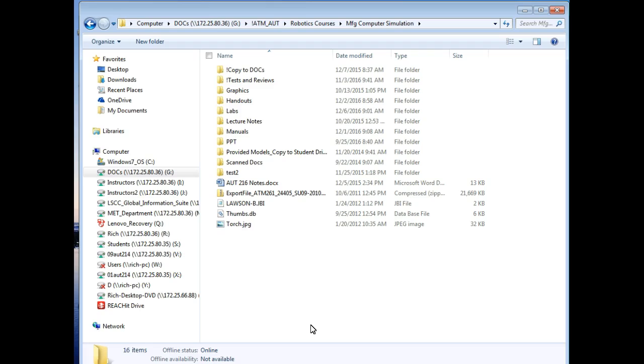Locate it, save it to the flash drive. No, you're out of sequence. You might get the compact flash to start off with, but number one, you're going to go over there and make a copy of it onto the controller under a different name. Okay, you understand? Then you're going to take the different name and copy it onto the compact flash. Then you're going to delete that different name off the controller. Okay, then you're going to transfer it into your computer. You're going to run it, see what it does.